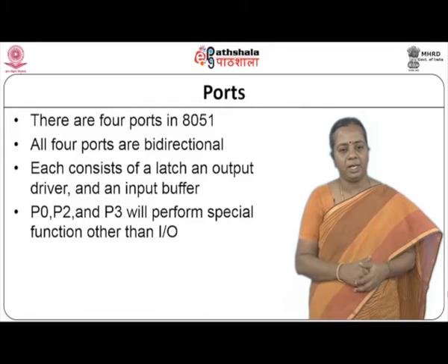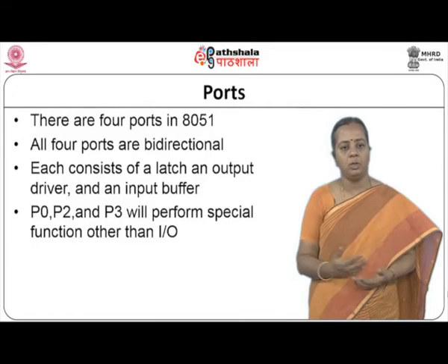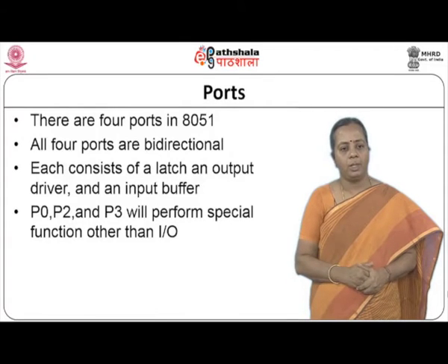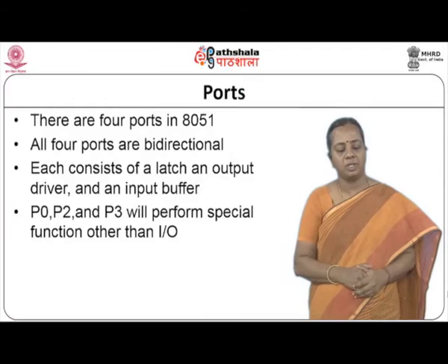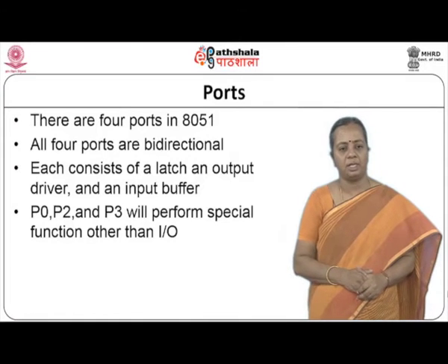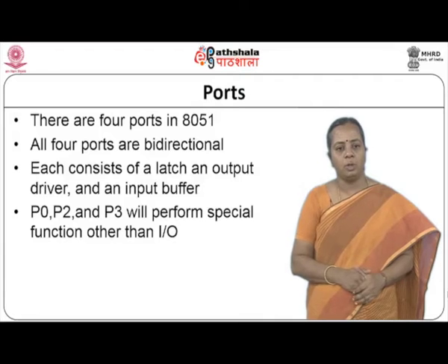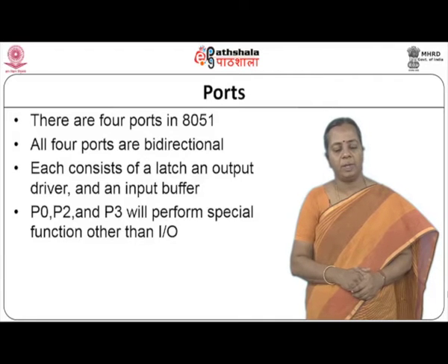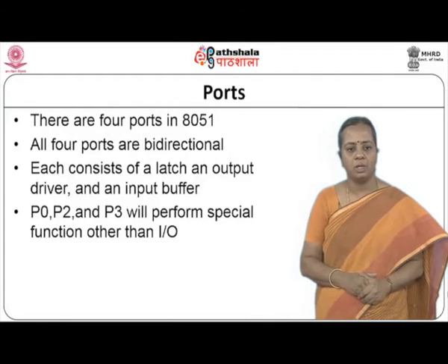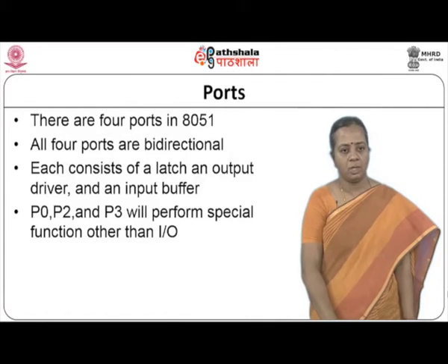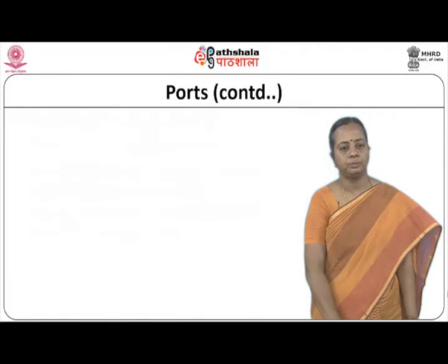You can read data from outside, or you can send data to outside also. So, when you are having a latch, these ports will have a latch and there will be an input buffer. When you are sending data outside, you use the latch, and when you want to read something, the input buffer is used. P0 and P2 are used, and P3 will perform special functions also.